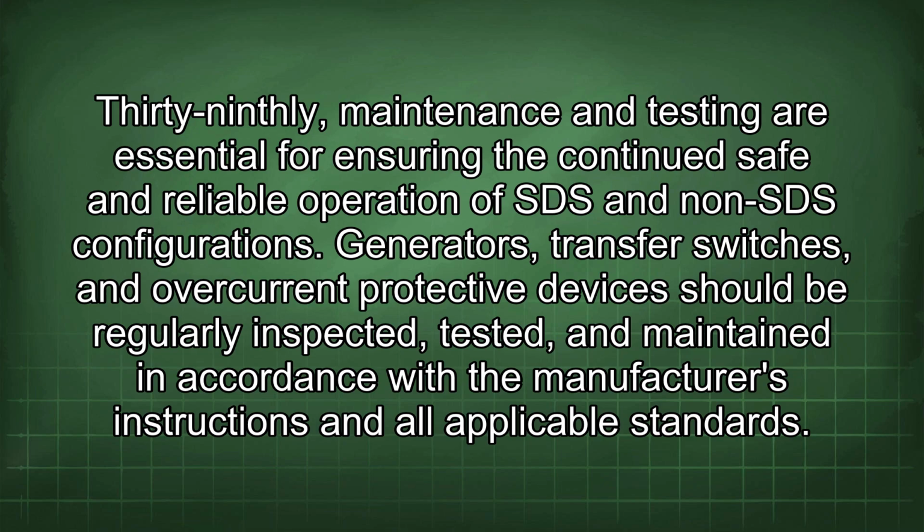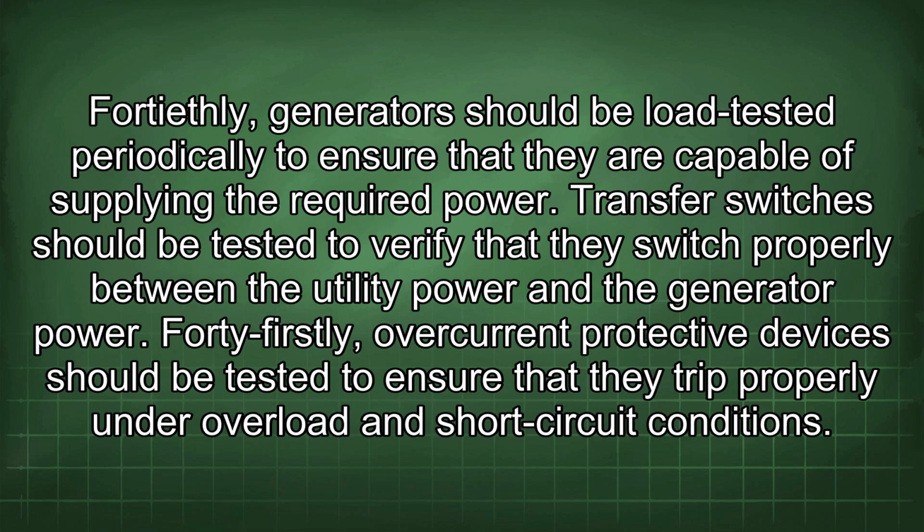39thly, maintenance and testing are essential for ensuring the continued safe and reliable operation of SDS and non-SDS configurations. Generators, transfer switches, and overcurrent protective devices should be regularly inspected, tested, and maintained in accordance with the manufacturer's instructions and all applicable standards.